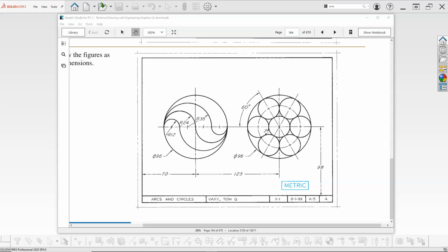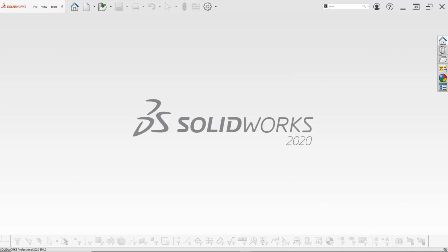One thing of note with this group, we're going to end up with 0 thickness locations at each of these tangency points, and that's going to prevent us from extruding this as a single solid body. So we can still manage it as multiple bodies, but that's one of the things to consider without overlap or without gap. Well, with gaps we'd possibly end up with multiple bodies anyway.